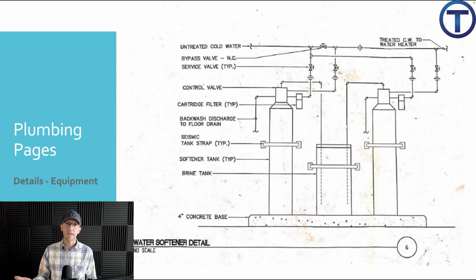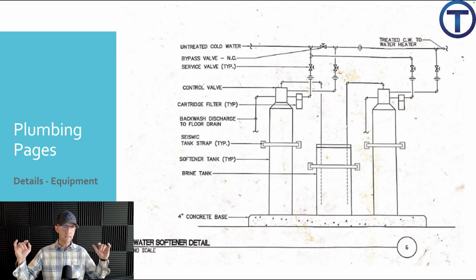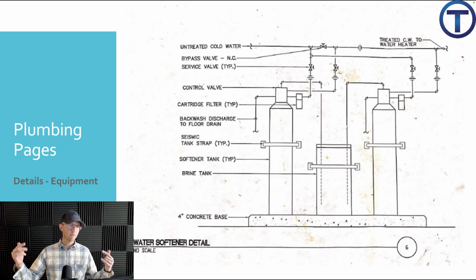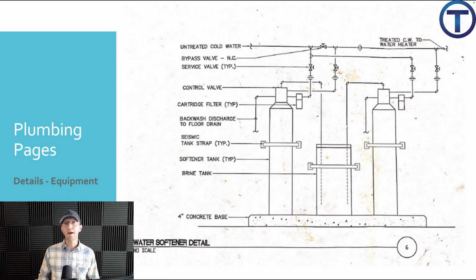Water's lazy that way. Same thing with the water heater, right? So this gives me everything I need to know as far as the valves, the T's, the unions, the softeners themselves. They're expecting me to strap them to the wall. We've got the brine tank involved, all the pipes, but I'm left with the ability to make sure that I pipe it correctly, pipe it in parallel so that it's going to work. And this detail is going to serve me well as I'm making my parts list.